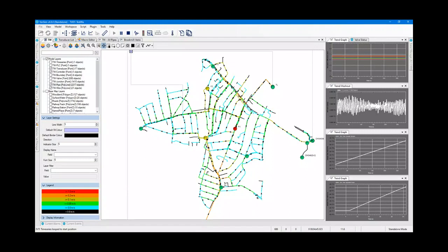With velocities and flow direction, you can see where flow goes in the system. You can see what velocities you've got in the DMA. You can understand how the flow travels, or the key arteries and the transmission parts of the DMA. So you can picture very easily where your flow and water travels to in the DMA, and also how long it takes to get through the DMA. So you can then look at age of water and water quality.